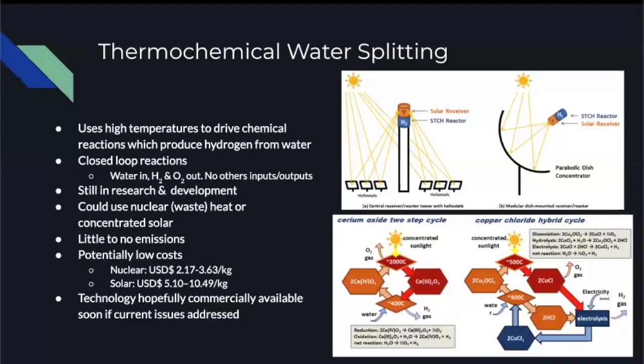such as first, the efficiency and durability of reactant materials for thermochemical cycling, which need to be improved. Second, we need efficient and robust reactor designs that are compatible with such high temperatures and heat cycling. And third, for solar thermochemical systems, the cost of concentrating mirror systems needs to be reduced. Either way, exciting progress continues in this field, which is leveraging synergies with concentrated solar power technologies and with emerging solar fuel production technologies.